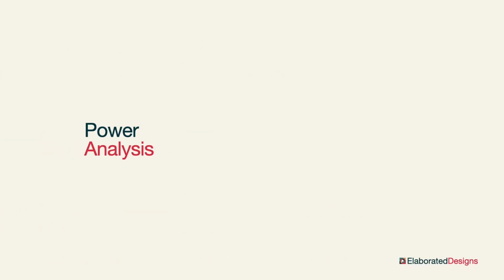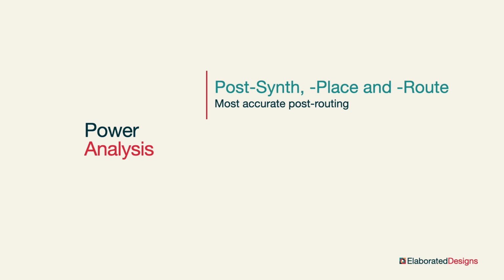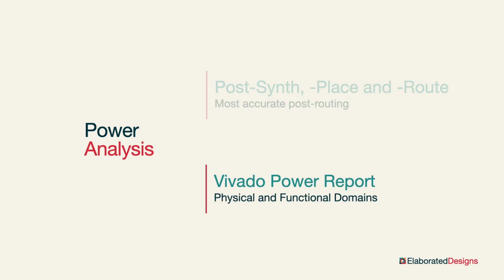Once we have described our logic, we can analyze its power draw at each stage of the development flow: post-synthesis, post-placement, and post-routing. The post-routing power analysis is the most accurate because it accounts for the exact logic and routing resources of the final design. We use the power report within Vivado to perform the power analysis.